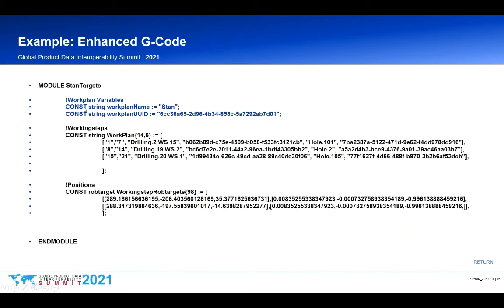So we're working with the existing construct of the G code, and we're essentially tagging. And that tagging is allowing us to bake in all of this additional information for work plans so the robots can receive it. And this wouldn't typically be in G code. G code wouldn't typically expect to have all of this additional information.